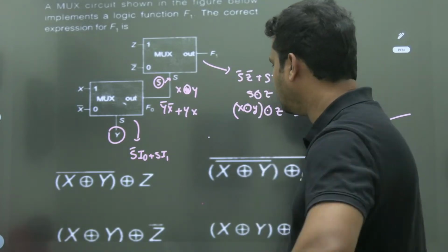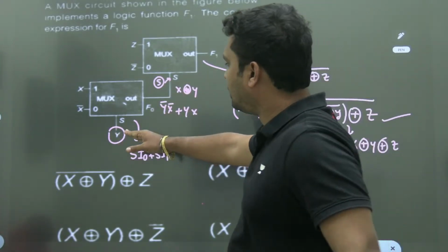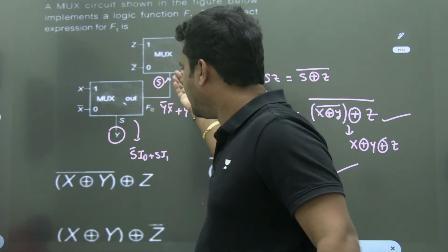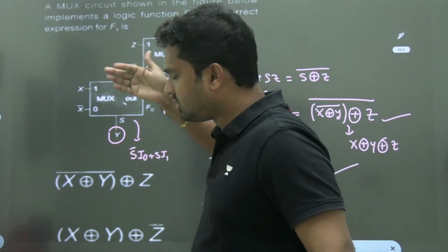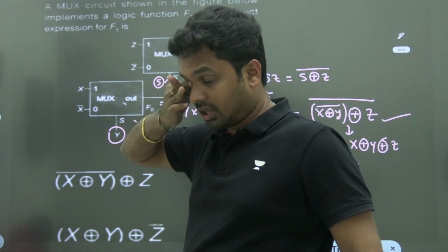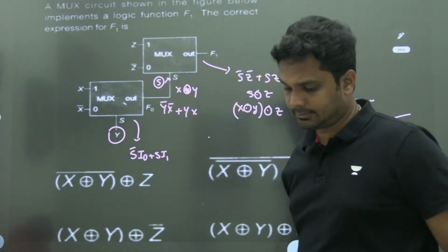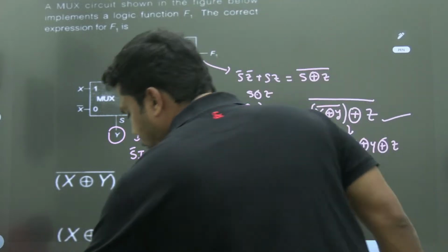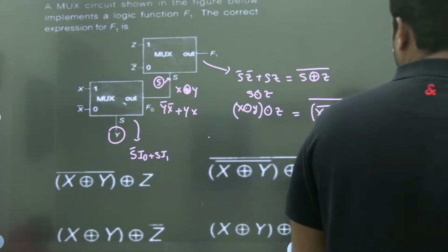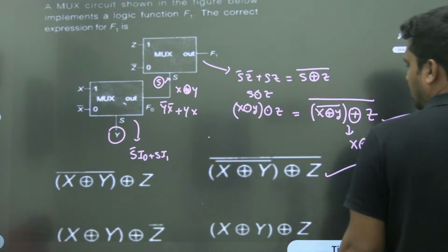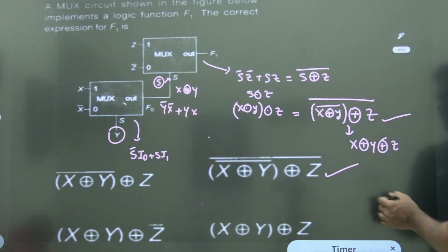Okay, so whatever you have given, this XNOR with this. Again, this XNOR with this. First, we do this. Bracket is taken to show the associative condition. Then this part is XOR with this. Don't take it as a complement of this one.